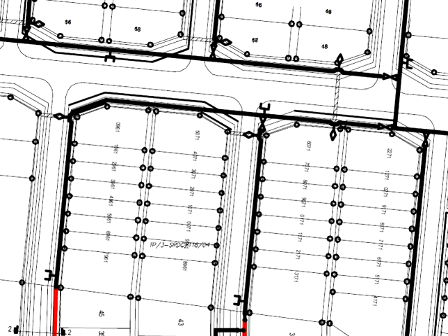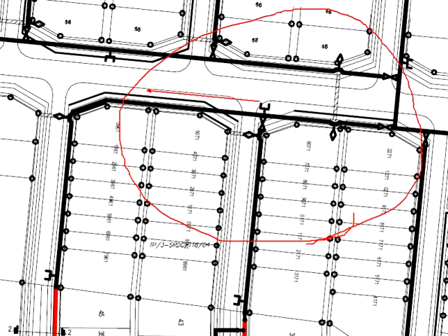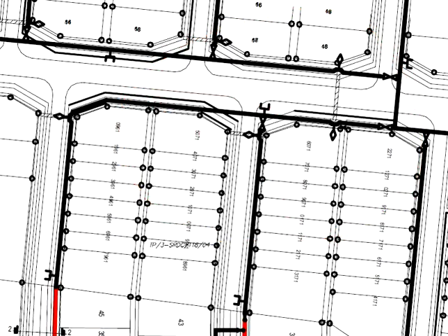Based on the requirement for typical residential areas, the clear distance should be around 90 meters. In other words, the coverage radius will be about 45 meters. Although it is stated that the radius distance is about 45 meters, we are still looking at the clear distance. Imagine this unit is under fire. The nearest fire hydrant, if it is located here, then you have to quantify the clear distance, whether it is within the 45 meters.